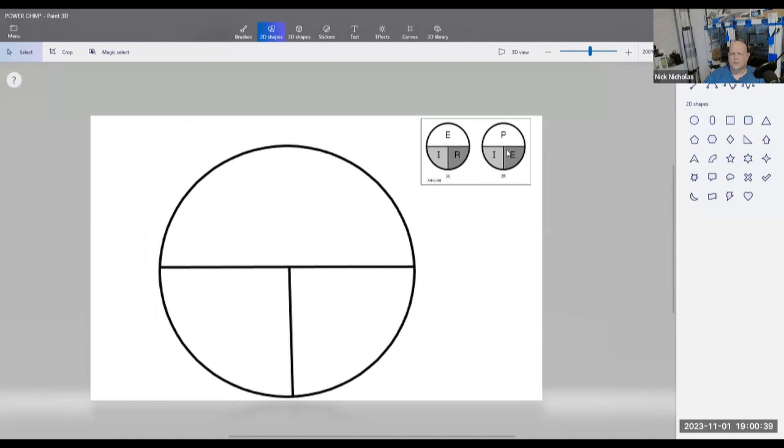When you take your test, you can have a scrap sheet of paper. In fact, normally at testing centers, they give you one. So when you have a question like the one we just had in the book, which was if you have 120 watts of power at 12 volts, how much current are you going to draw? You know you got this equation, P equals IE. Well, they gave you the power, so draw yourself a circle.